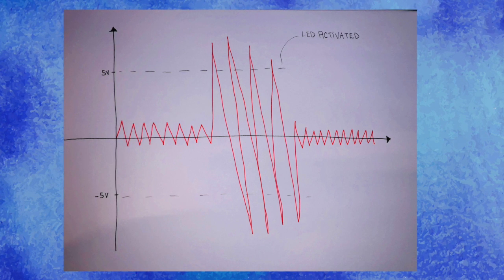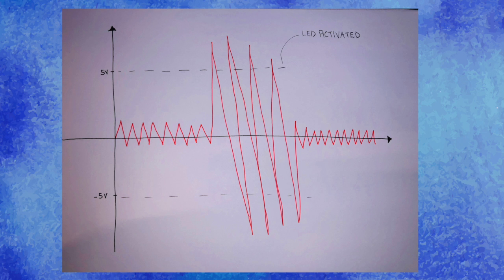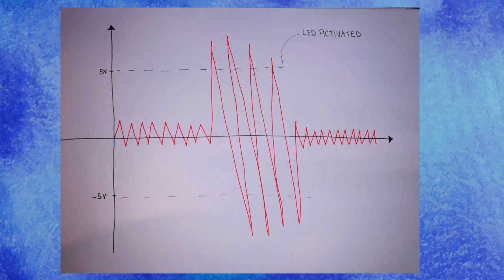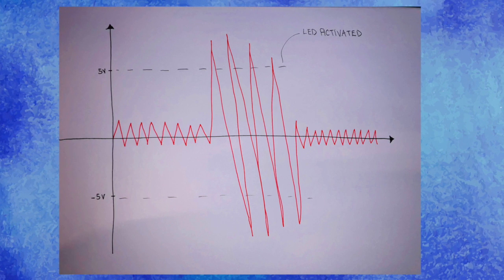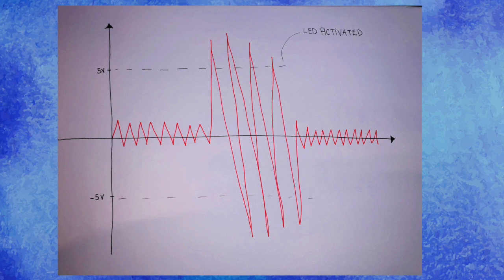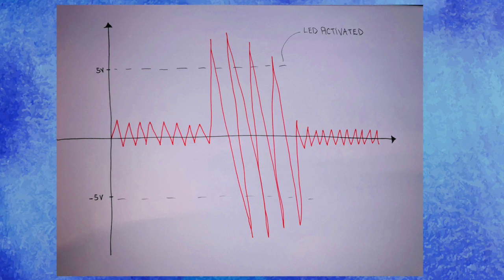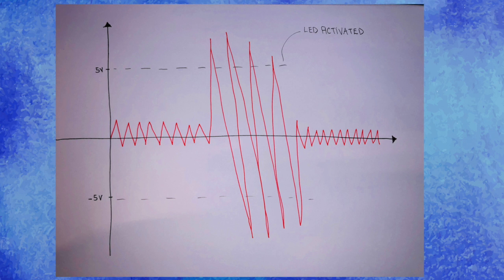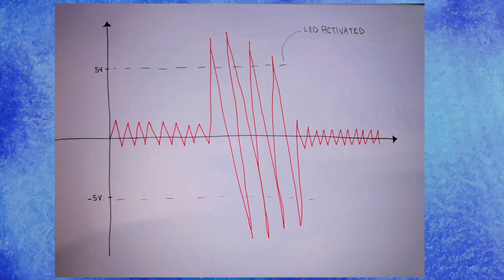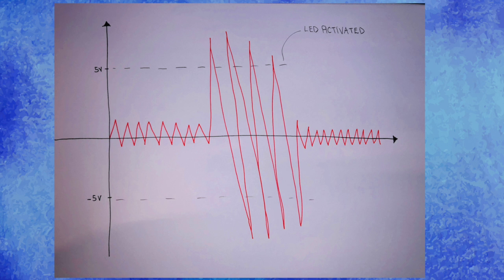When the LED is constantly on, the gain is too much, which means we're amplifying the noise as well as the EMG signal. We want to isolate the EMG signal, so we have to lower the gain so it doesn't amplify the noise as much. When the LED is constantly off, the gain is too low and the amplifier doesn't amplify the signal from the EMG enough.